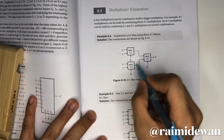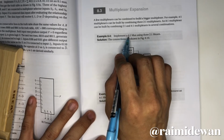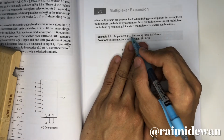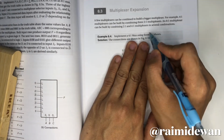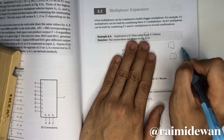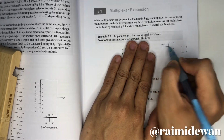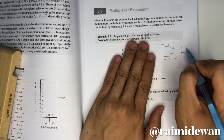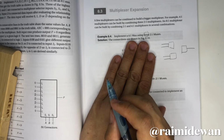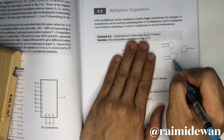So here you can see, we implement a 4-to-1 mux using 2-to-1 muxes. Please see this. It means that you have a 4-to-1 multiplexer, which means you have 4 inputs, and of course you only have 1 output. The special part is that a multiplexer must have data select, so don't forget to draw the data select input.